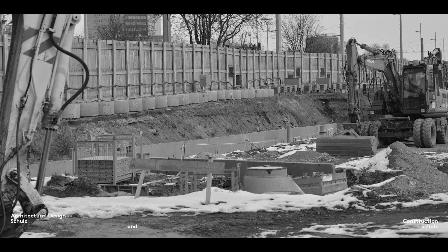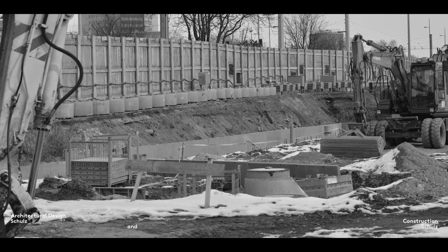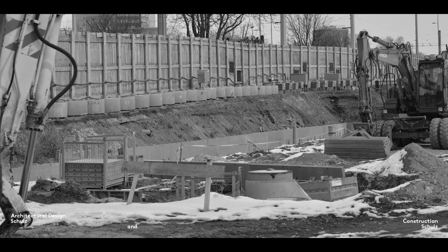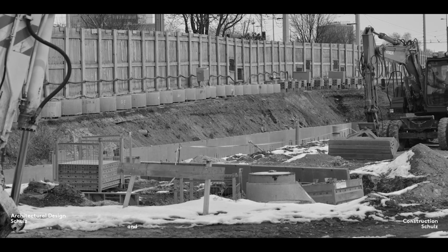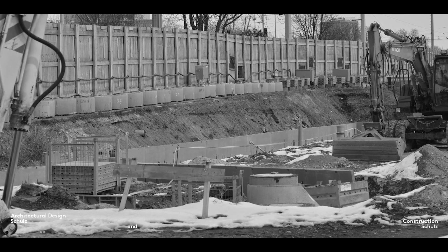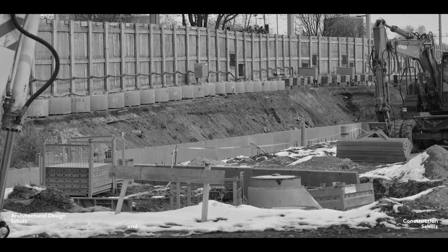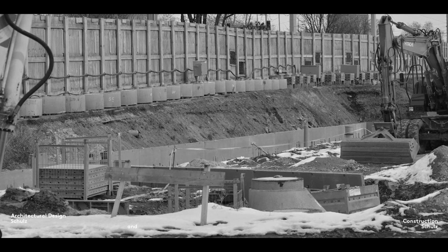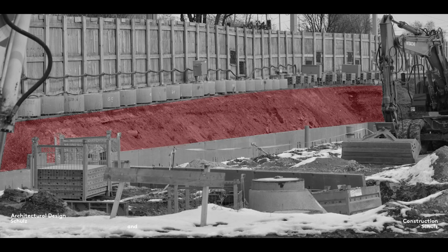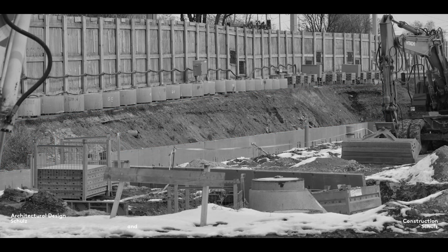Treatment of the edges is particularly important. As you will know if you've ever tried to dig a hole in the sand, the walls have a tendency to collapse. To prevent this, the walls need to be sloped or banked at the shallowest possible angle. The angle of banking depends on the type of soil. Foundation pits are usually banked at an angle of between 45 degrees and 60 degrees to the horizontal, as you can see here. If the ground is unstable or there's no space for banking, the walls of the foundation pit are supported by a pit lining instead, as when digging a grave.